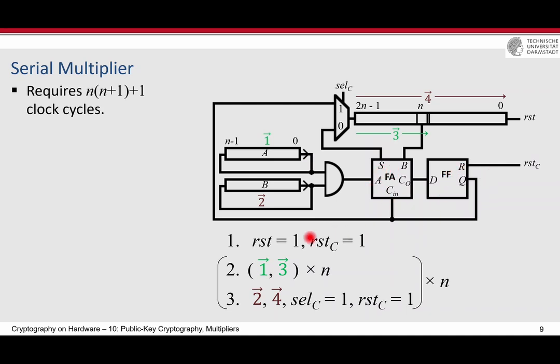And as I said, this construction is there, and then there is a multiplexer here which selects whether the output of the full adder is stored here or the output of the carry. Because when you add everything, the last bit should also be stored here in this register when there is nothing to add, and then the last carry should be stored in the register.